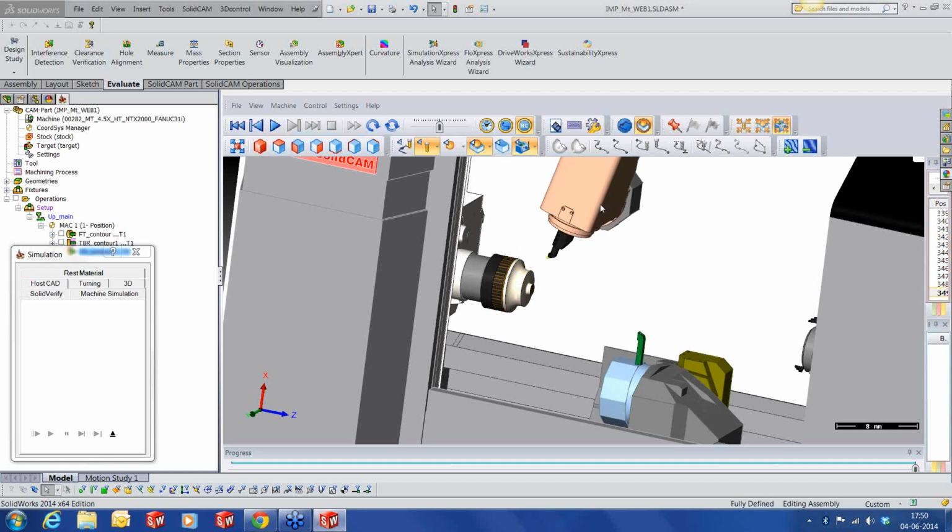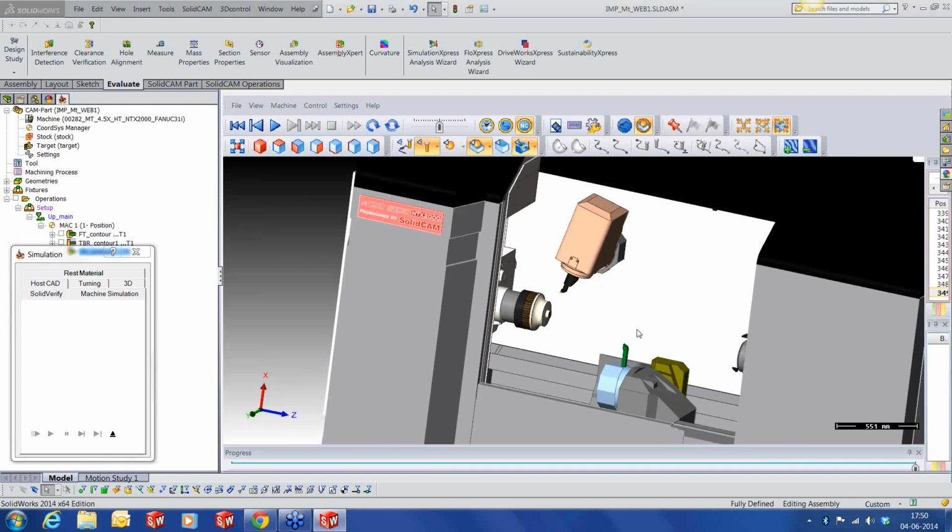Now this can be dangerous when I'm trying to do a 5-axis operation. If the upper head is going to tilt almost to 90 or beyond 90 degrees, then there's a possibility that the head might touch somewhere either on the tool or on the turret itself. So I need to move the turret back to a safe position.